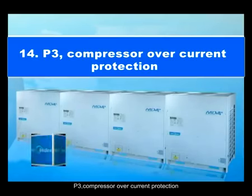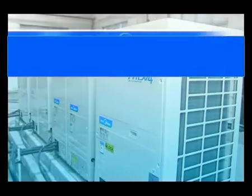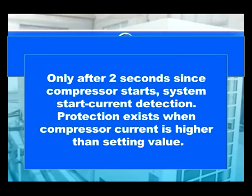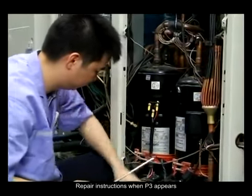E3. Compressor over current protection. Only after 2 seconds since the compressor starts does the system start current detection. Protection exists when the compressor current is higher than the setting value. Repair instructions when P3 appears.